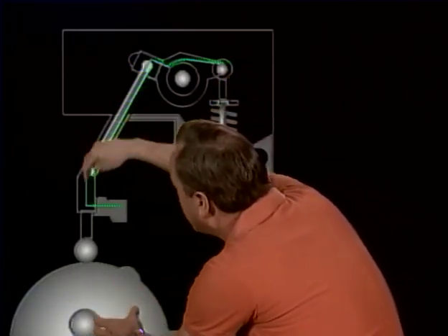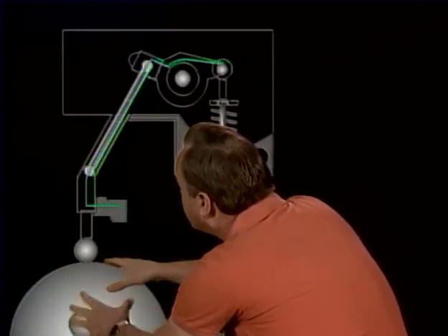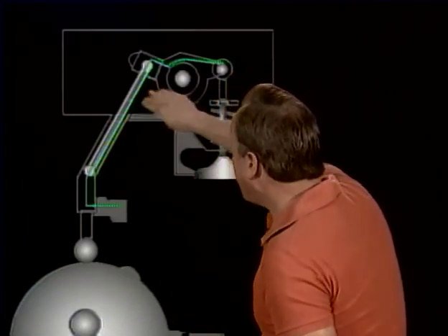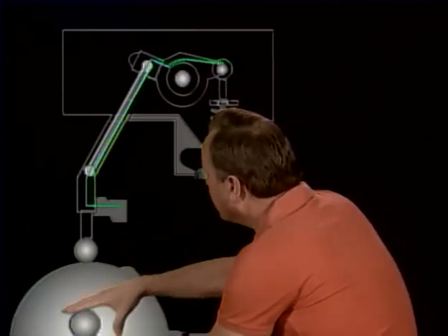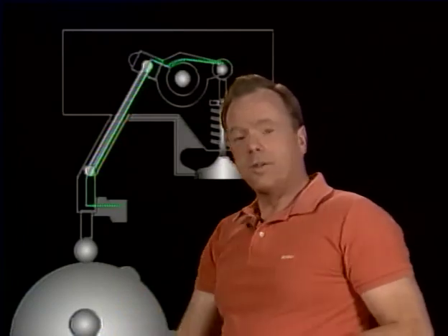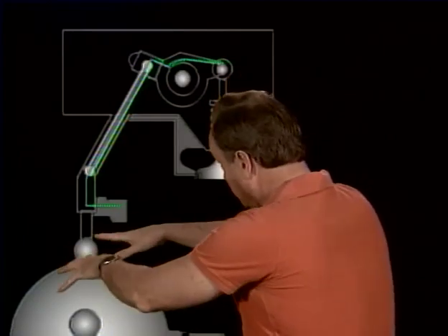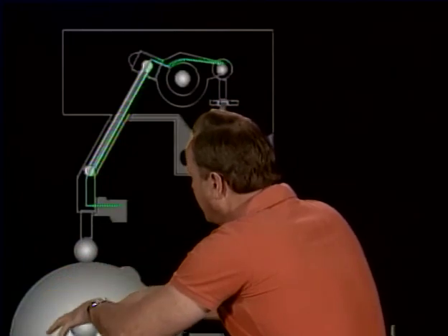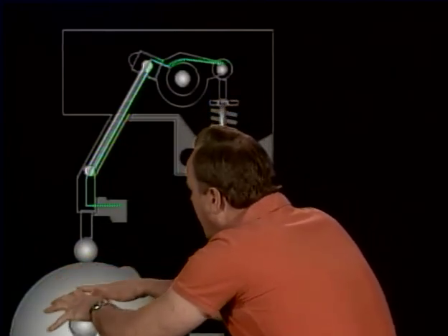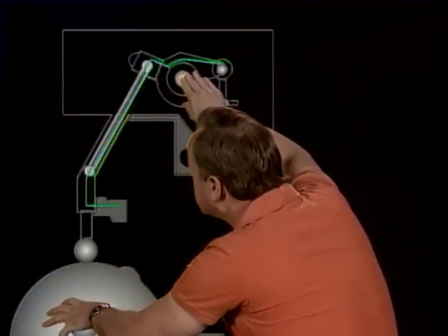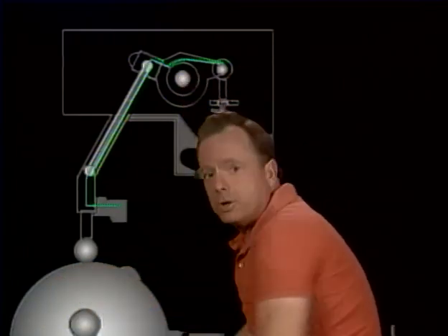What holds them in place if they float around in a bearing? And the answer is the spring tension on these push rods holds the cam ring in place. Now, the point they want to make is if you are adjusting the valves in a radial engine with a floating cam ring, this cam ring can float around. How do you do it to make sure that you are standardized, make sure you have the proper valve clearance? And the answer is you've got to make sure that the cam ring is tight against its bearing. You do that by taking this tension off the other side, make sure the cam ring is tight at the bearing, then adjust the valves, and that way you make sure you have the proper clearance.